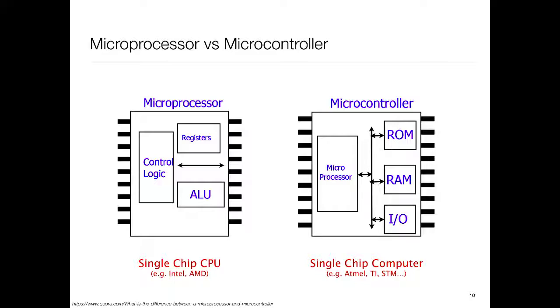There are so-called embedded DRAMs, which do exist, but by and large you would see SRAM and some sort of read-only memory, usually flash. Whereas with microprocessors, most systems end up using DRAMs just because they give you much more bang for the buck.